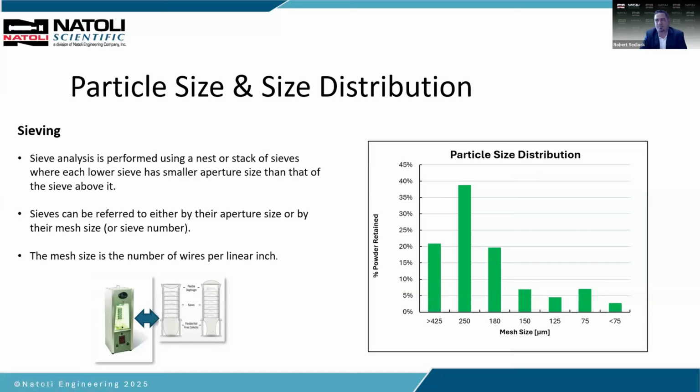Density is very important to us. Bulk density is the apparent powder density in defined conditions. So we pour our material into a graduated cylinder, and we measure what the mass over volume is. We like to see bulk densities at 0.25 grams per cc or 0.25 grams per ml or higher. Obviously, the higher, the better. 0.5, 0.6, 0.7, we're getting higher.